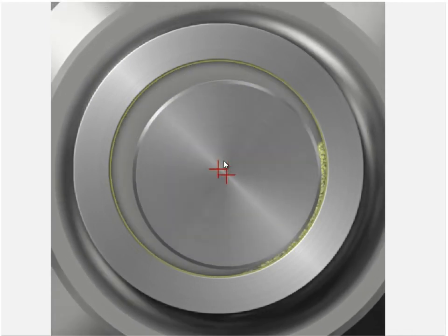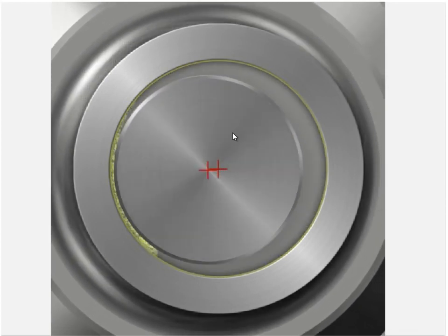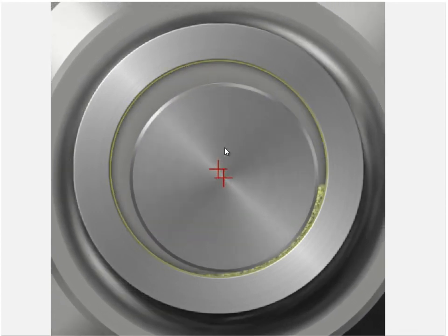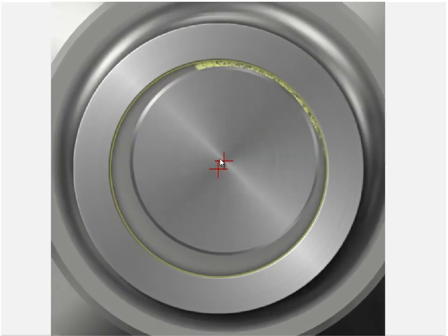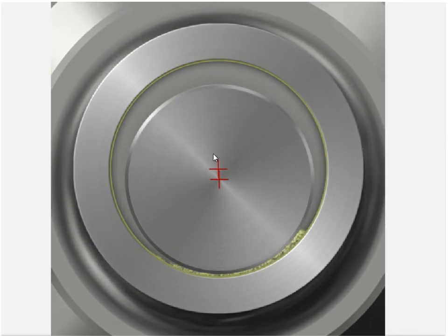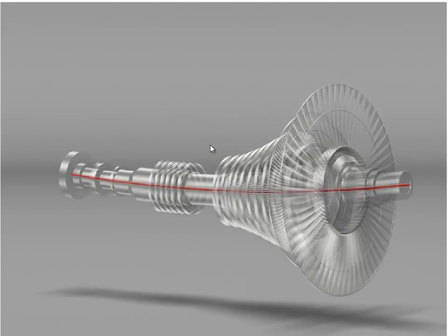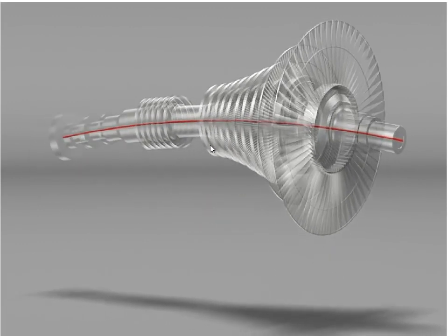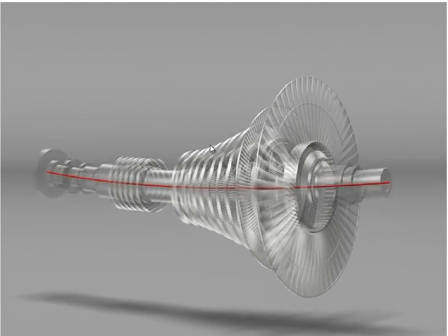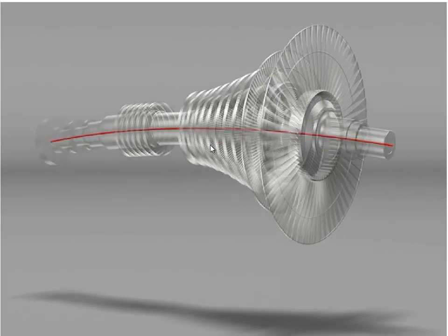It can't be any higher at this particular location. There can't be any more motion because it would start wearing away the bearing. But this is the sort of thing we'd like. We want to know in essence what the shaft is doing, what the center of the shaft is doing, because there are other faults in addition to unbalance and misalignment and preload and these sorts of faults. We're interested in the rotor dynamics as well, particularly as we go through the critical speeds.